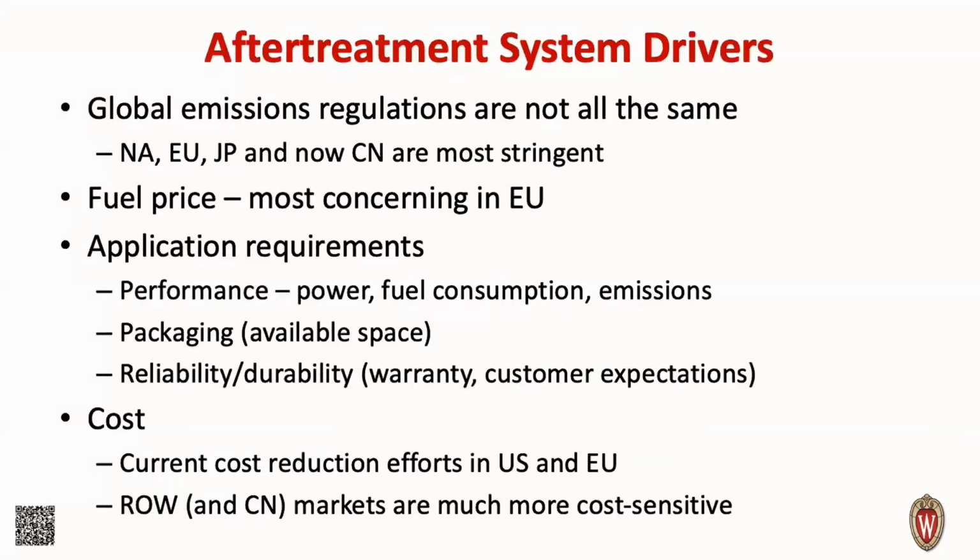What drives after treatment systems? Well, the whole reason we have to have them is because of global emissions regulations, which are not all the same. Fuel prices drive after treatment system design. The application requirements, whether we care most about performance or packaging or reliability, and then costs, right? Current cost reduction efforts of what's called thrifting of those platinum group metals is another thing that we work on.